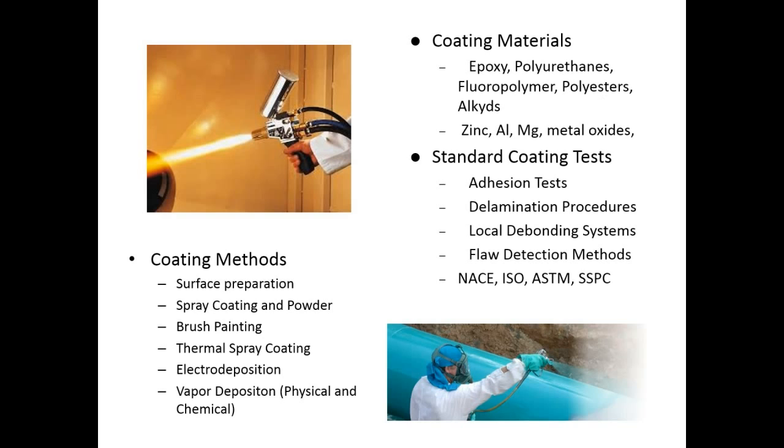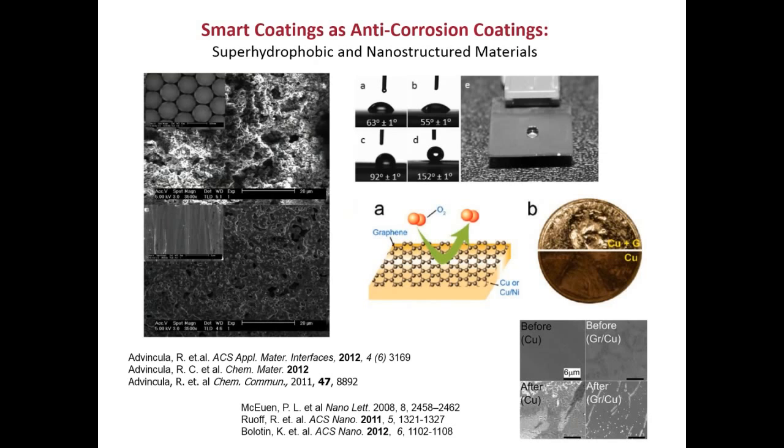Now, in our lab, and this is what we focus on, bringing in nanotechnologies for the coatings industry, we focus on two things. One is the creation of more superhydrophobic structures. And we have proven that better superhydrophobicity or even super oleophobicity is very good for preventing corrosion as well as self-cleaning properties.